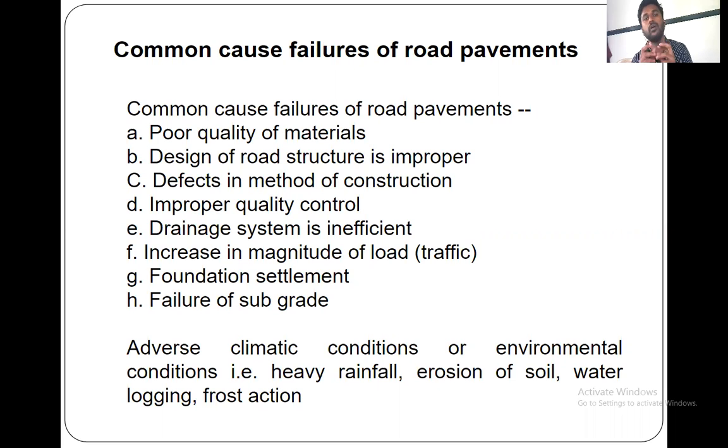The bond between them will be loosened by the water and by the traffic. Once the bond gets loose, ultimately the aggregate tries to come out. So due to that, cracks or potholes will be there. So a proper drainage system is also necessary to provide.